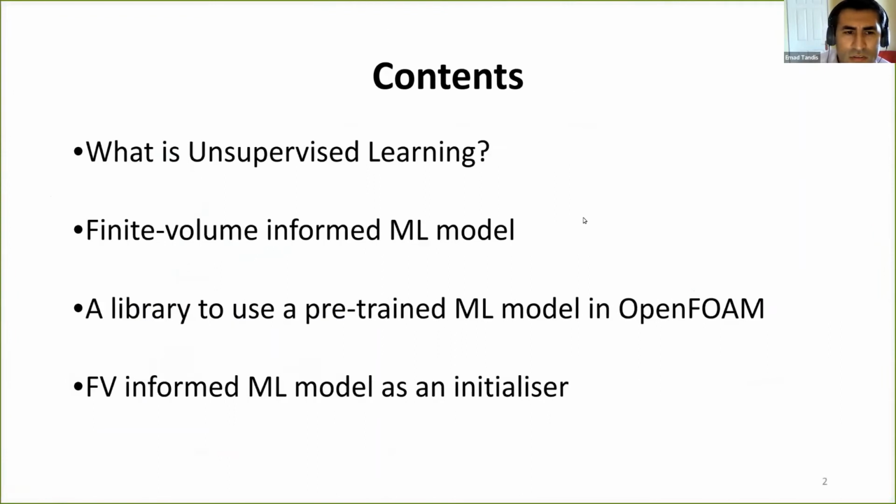Okay, the contents of this talk would be about an introduction of unsupervised learning, then a finite volume informed ML model, which is our approach. And then we introduce a library to use a pre-trained model in TensorFlow and in OpenFOAM. It can have a general usage for turbulence modeling, for any other application. And finally, I will be talking about how to use our approach as an initializer in the solids4foam solvers.